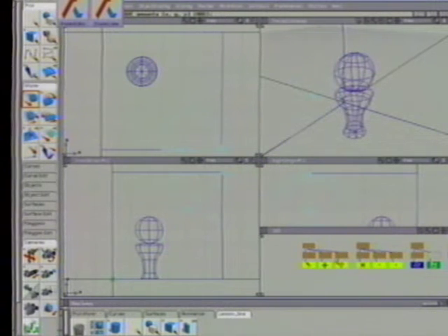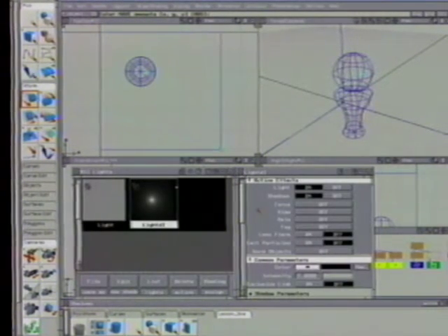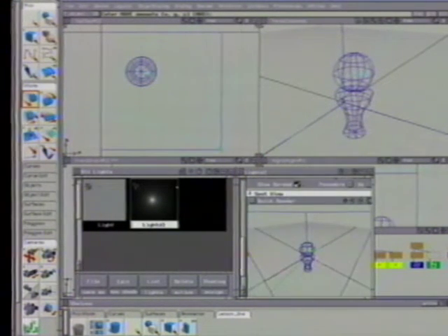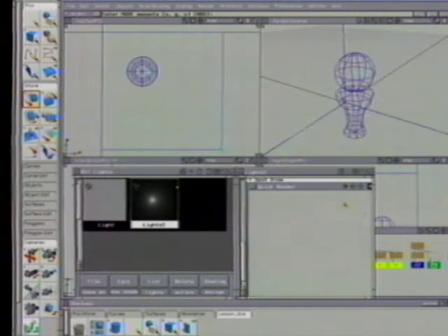Now move it to the bottom corner in the top window. Next, pick only the look at vector of the light. Move it in the modeling views until it is pointing at the sphere. Now, maximize the light lister and editor. Scroll down to the Spot View section and click to open. This view now shows the scene from the point of view of the light.